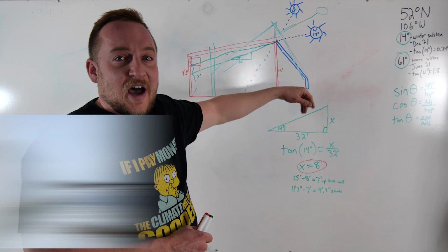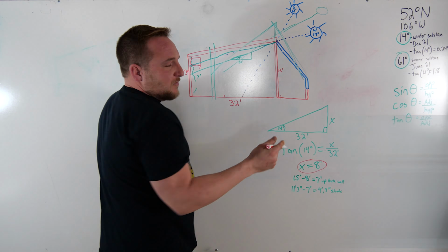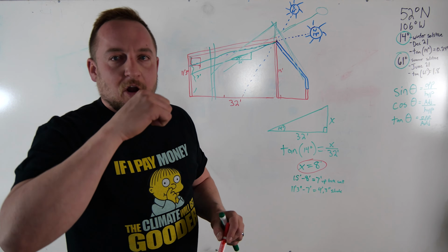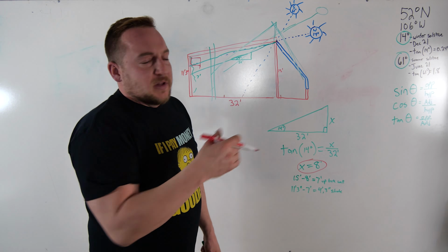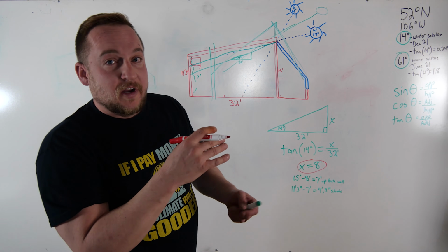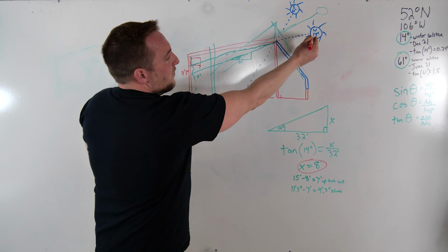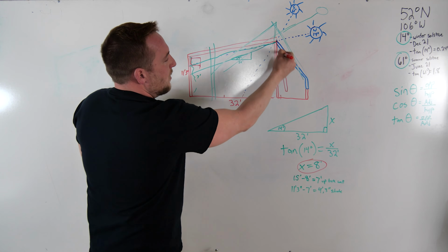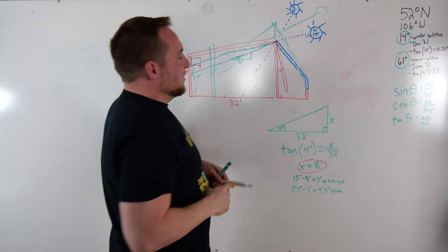If you're using glass, it reflects the light. So if I was using glass, and they didn't invent polycarbonate, which refracts light, then it would just be a winter use greenhouse. It wouldn't serve much purpose in the summer, but I would do perpendicular to the winter solstice, so 14 degrees, so it drives directly perpendicular into the glass.